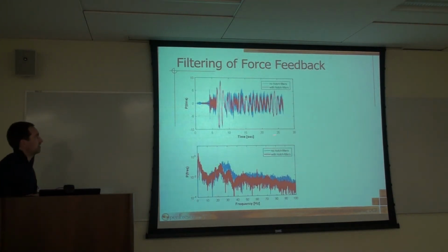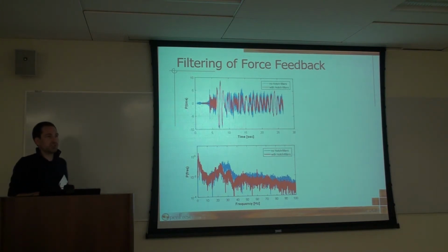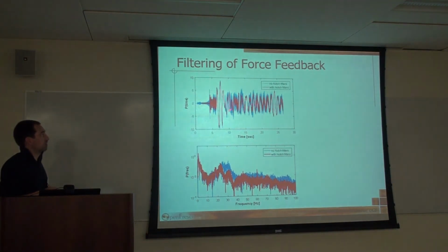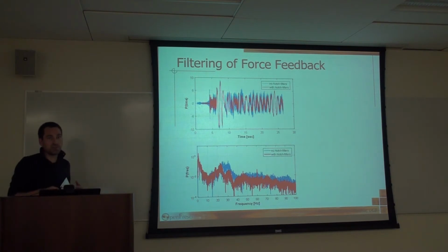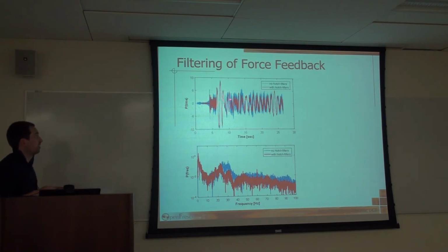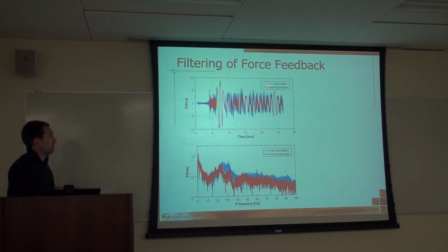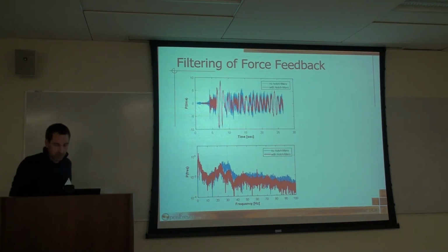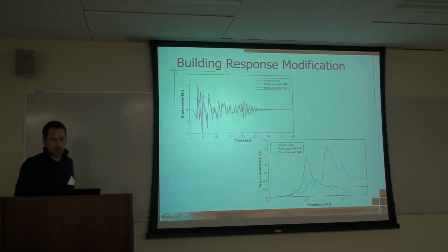One thing that we were facing as a problem is that we're measuring forces during these tests from load cells. We're not doing an observer. But even with our load cells, we still have a lot of noise on those. It's a lot better than doing an observer, but the noise is still there. And so we started filtering. We had to create some notch filters to take out some of that artificial noise that was there. And so we were able to improve this. But that clearly needs more work to figure out exactly what we want to do there.